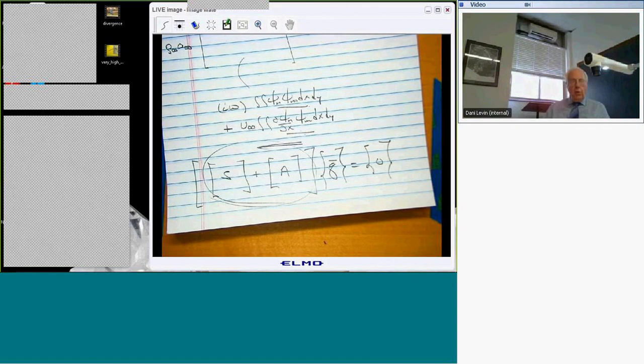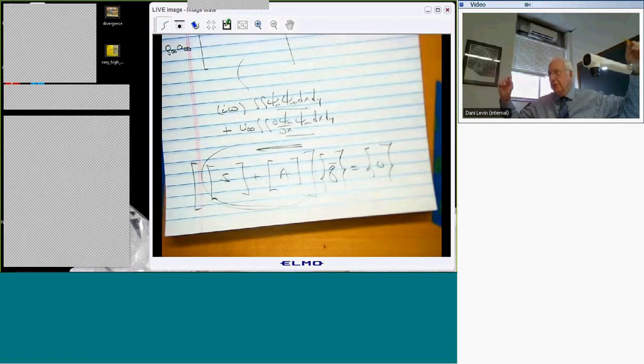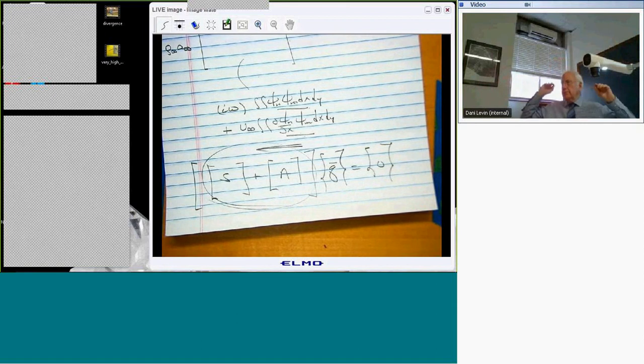Or you can multiply out this determinant and get all the terms, and this is what I was looking for, all the terms in its great glory. What kind of an equation in terms of omega would that be? As opposed to transcendental, it's not transcendental. What other kind of equation could it be? That's a polynomial. That's what I was looking for. It'll be a polynomial in omega, right? And so I just need to find the roots of that polynomial.